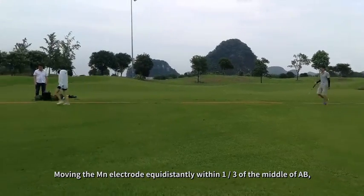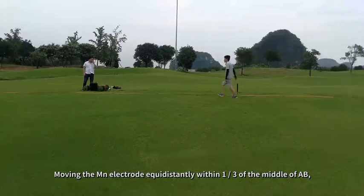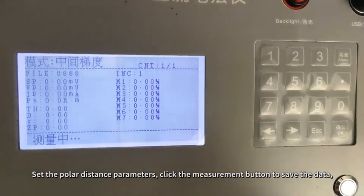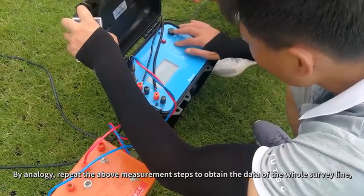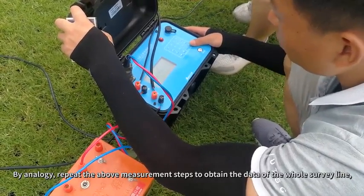Moving the MN electrode equidistantly within 1/3 of the middle of AB. Set the polar distance parameters. Click the measurement button to save the data. By analogy, repeat the above measurement steps to obtain the data of the whole survey line.